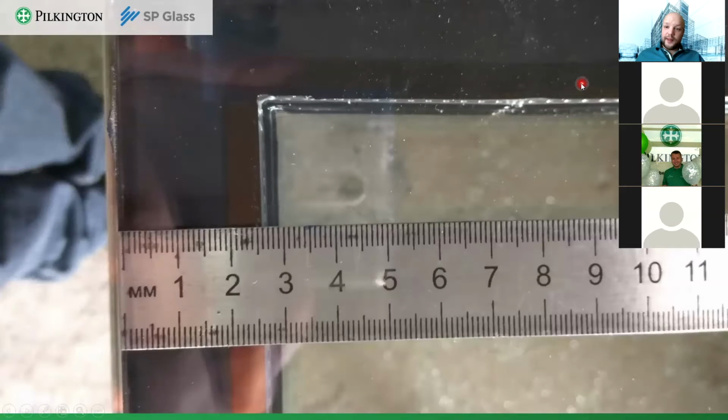the butyl should be always positioned evenly on the borders of your spacer. You should not have any breaks, because this is a critical fault. For example, here you can see a perfect application of your butyl, even everywhere, even on the corner, because corners and spacer connections are the weakest point in all of the IG units.